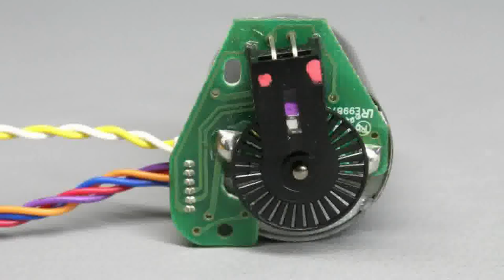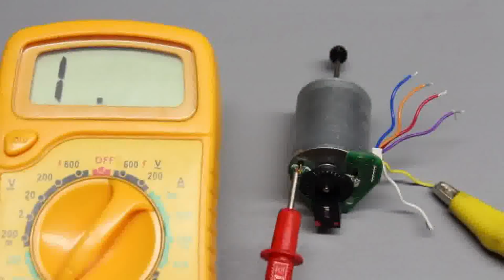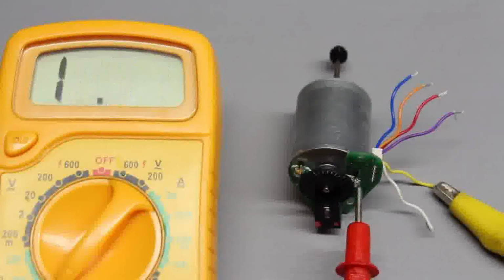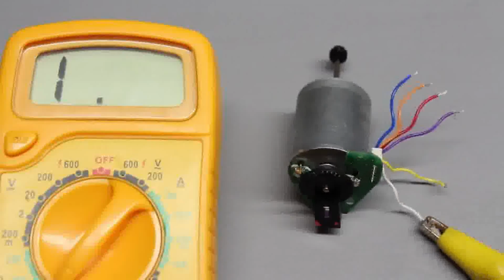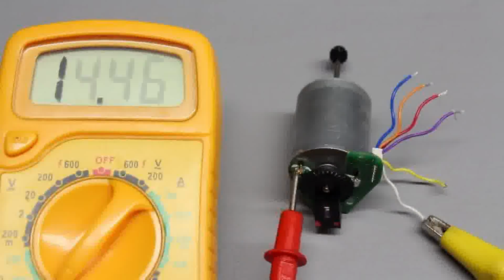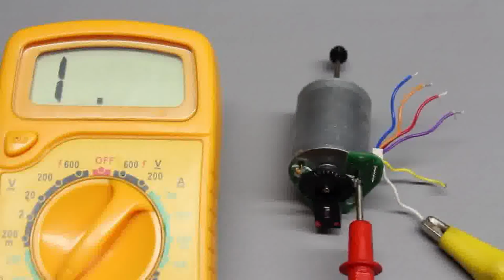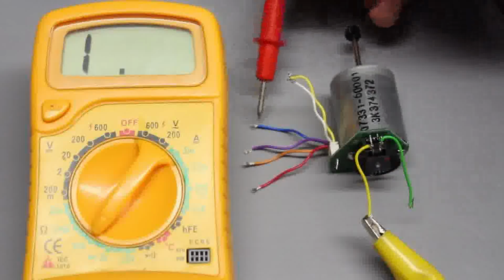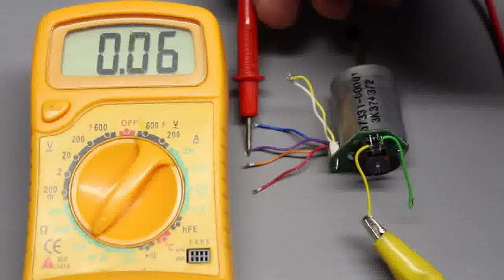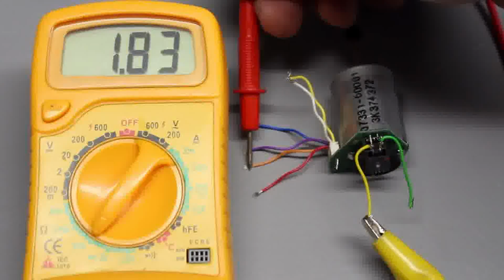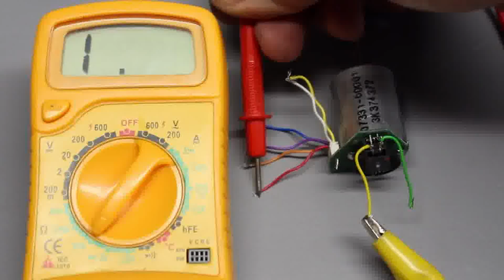Another sensor unit I found in a printer is mounted on the rear of a DC motor. The yellow and white pair of cables is very likely joined with the terminals of the motor, which is obviously right. The remaining 4 cables are tested as done before, using a multimeter with the LED pins as reference points.